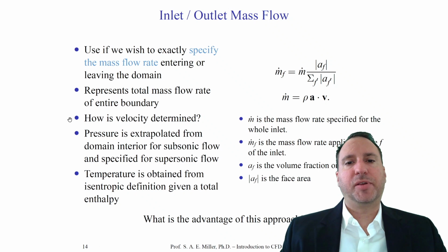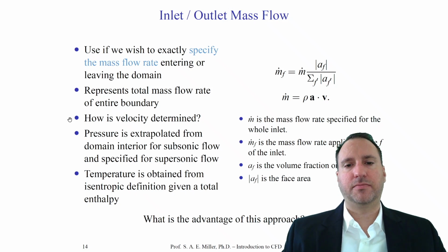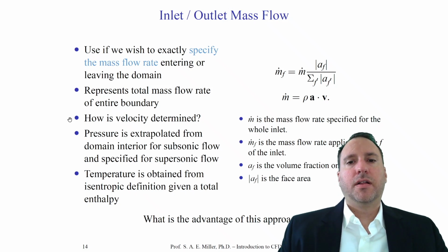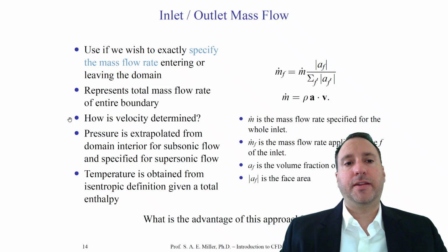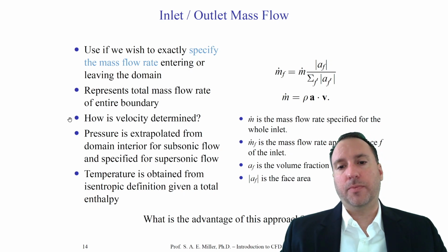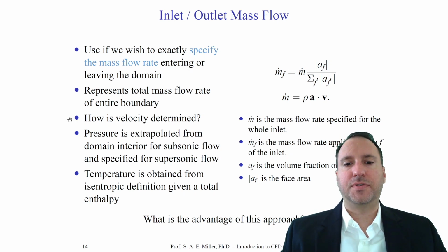These are very popular in incompressible solvers, and a lot of students like them because, of course, you've learned volumetric methods originally in your classes. These might be where we simply set the mass flow rate at the inlet of the boundary and the exit of the boundary. If we only have one inlet and outlet of the domain, we would make sure to have our mass flow rates of the inlet and outlet be equal. This can be enforced explicitly through some solvers, but usually as a user, you'll have to do this yourself.